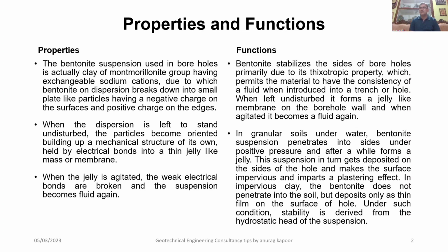In granular soils underwater, there is a need for bentonite suspension, because in sandy soil boreholes under water, there is a fear of the borehole collapsing. There are always chances of borehole collapsing. Therefore, in order to stabilize these boreholes for concreting purposes, so that the reinforcement cage can be put in and concreting can be done, we have to use this bentonite suspension in granular soils underwater.